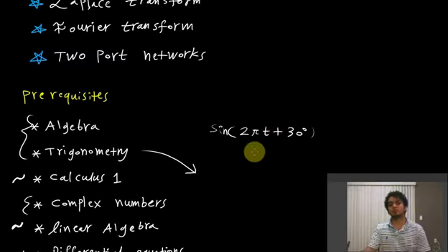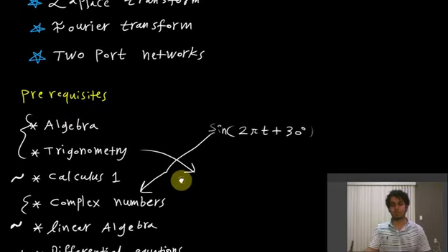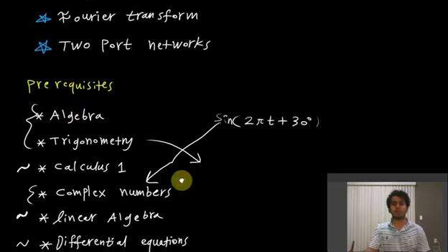So what you do is turn your quantities into real and imaginary parts, which are complex numbers. You do the algebraic manipulations, the complex algebra, and once you finish, whatever the manipulations are, addition, subtraction, multiplication, conjugation, you basically convert the quantity back into either sinusoid, polar form, or exponential form, depending on what the problem asks you.